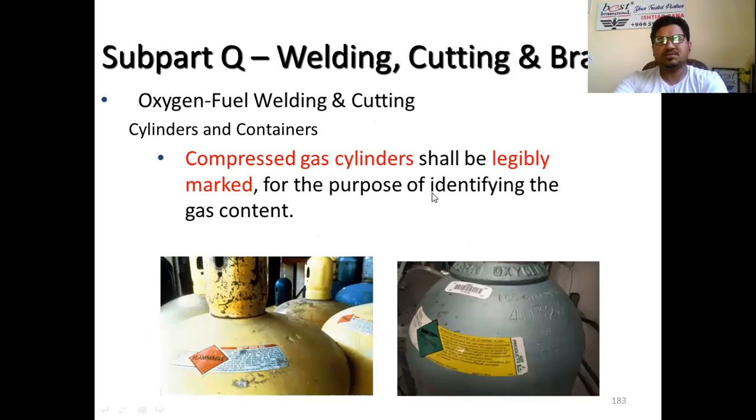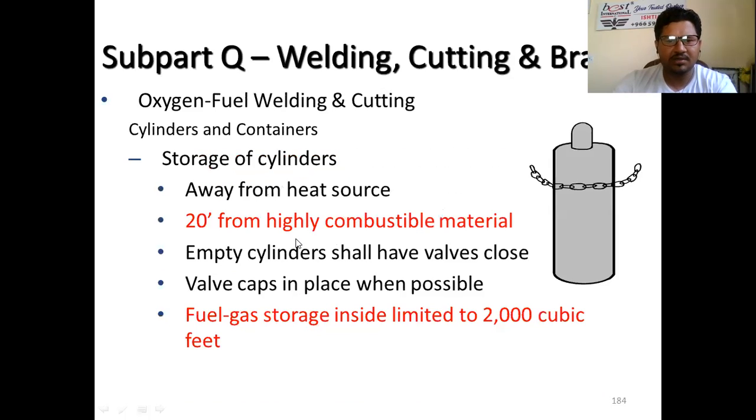Compressed gas cylinders must be legibly marked for the purpose of identifying the gas content. And make sure you have the storage of cylinders, quite technical information, like 20 feet from highly combustible material. Empty cylinders shall have closed valve caps in place when possible, and make sure the fuel gas storage inside is limited to 200 cubic feet.